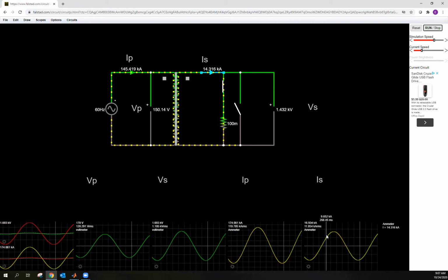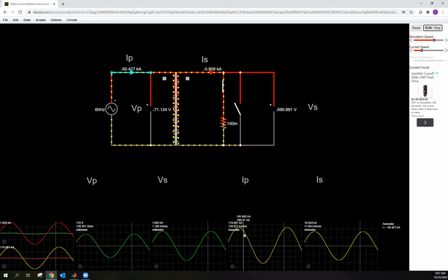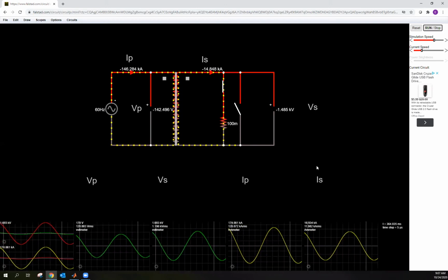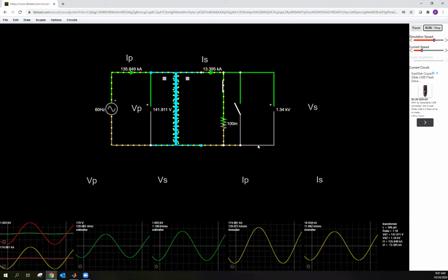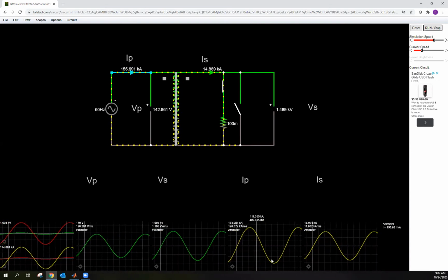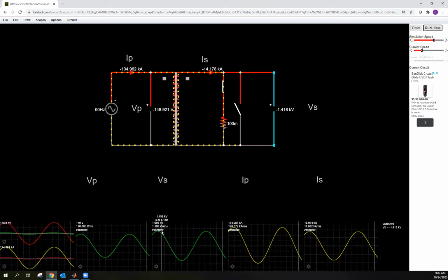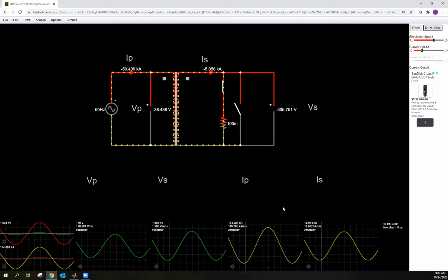Now, like I said, this is a bad situation. We don't want to be doing this, right? For various reasons, you don't want to have 120 kiloamps RMS. It's totally unreasonable. But because of the choice of inductance, which is also unreasonable, 0.0001, it's crazy small, it is at least behaving like an ideal transformer, okay? Everything's nice. We're all happy here.